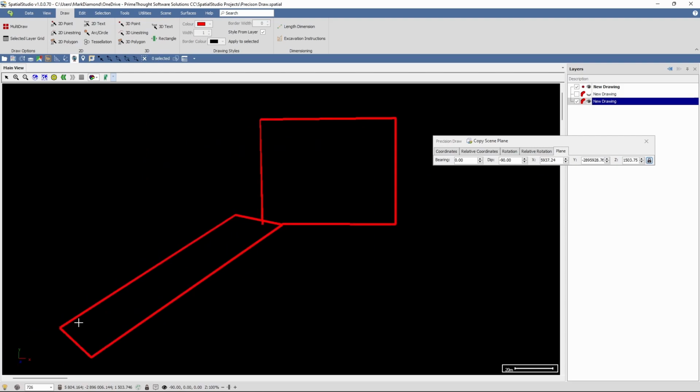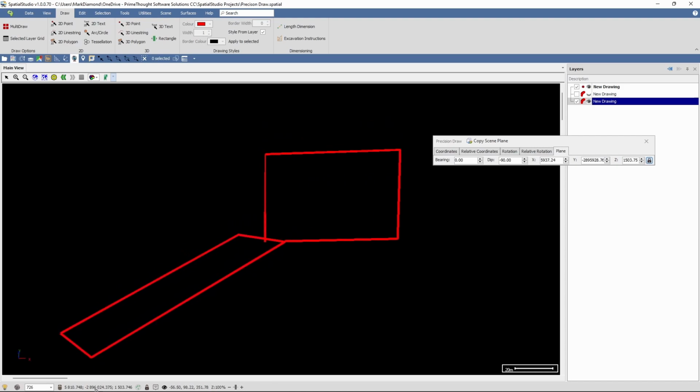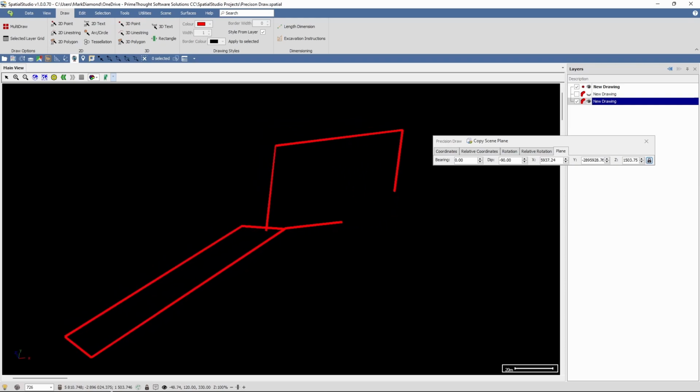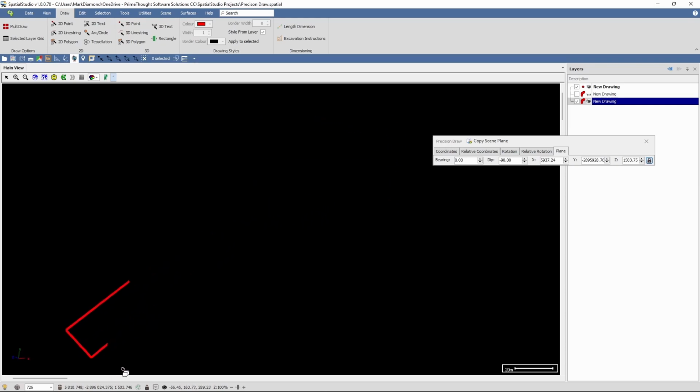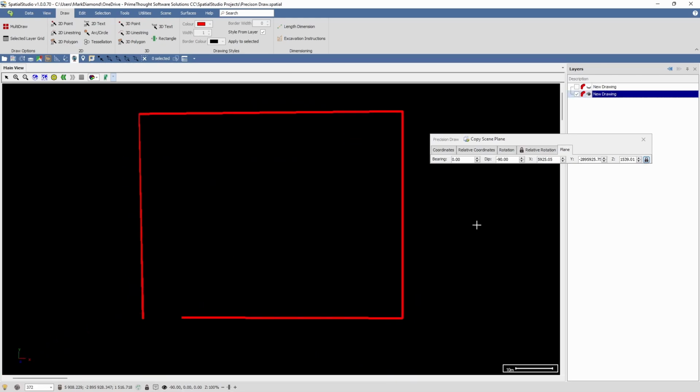And you can see the line string that I drew actually is locked to this view plane over here, even though I had my view orientation changed around. It locked it to this view plane as I drew it and made sure it was drawn on this same view plane as this other drawing over here. Now, of course, the view plane is also the exact view depth that you're at that has been locked. So similarly, if I go to a different view depth and draw over there, it would still honor and lock it to the original view depth of the view plane that I locked, at the exact elevation where that was.